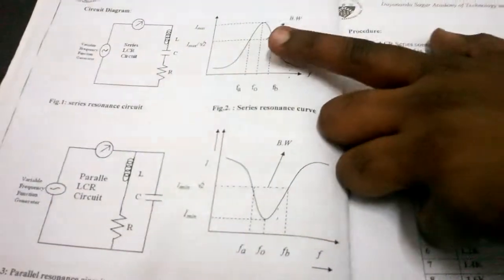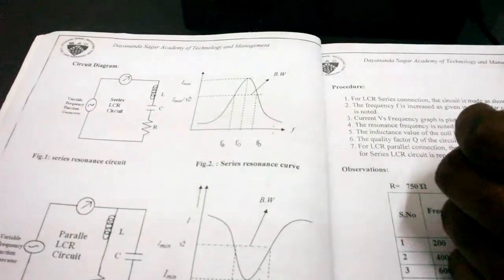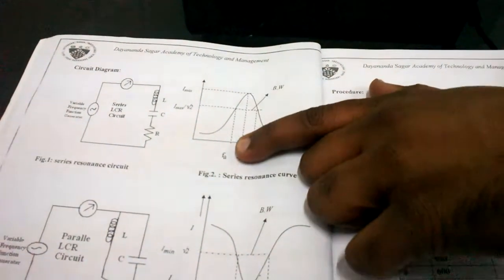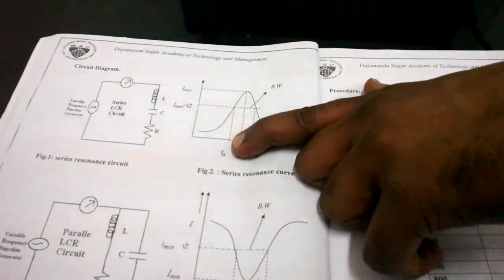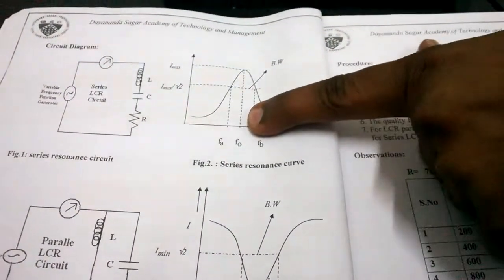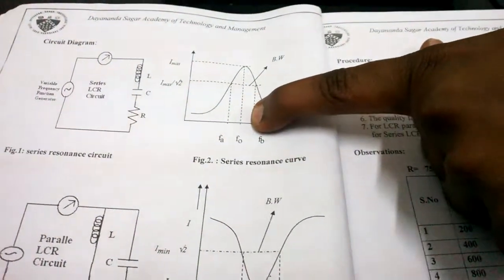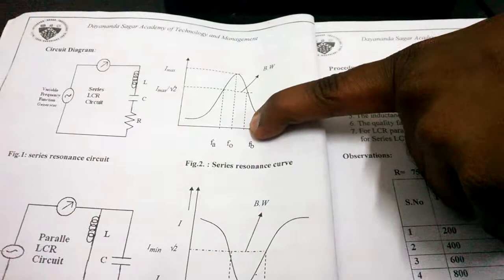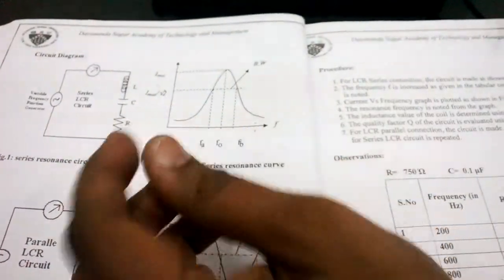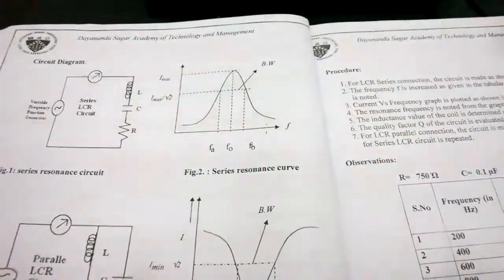Bandwidth, in the sense of radios or FM tuning circuits: if you keep on tuning, once it reaches this lower frequency, we will get a signal, but the voice is not clear. If you keep coming towards the resonant frequency, we will get clear voice, and if you keep on tuning again, we lose the signal at this frequency. The range of frequencies where we get signals, that we call the bandwidth. That's what we are calculating from here.